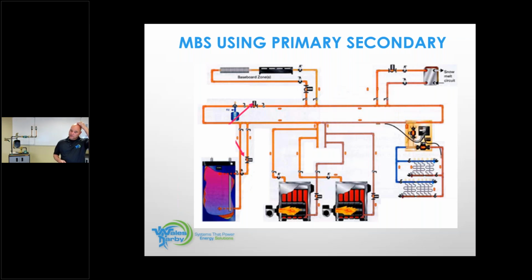John, I'm sorry to interrupt you there. Go ahead. Gentlemen want to know, so you do need reverse return since you have extra pumps? Not because of the extra pumps. We would always do reverse return on the boilers so they do the same amount of work. This boiler right here is the second one in, but the first one out. That's just to make sure we keep the boilers operating at the same temperature and around the same input rate if they modulate. These look like cast iron oil boilers, so they're on and off, but they'll be more even on temperature.